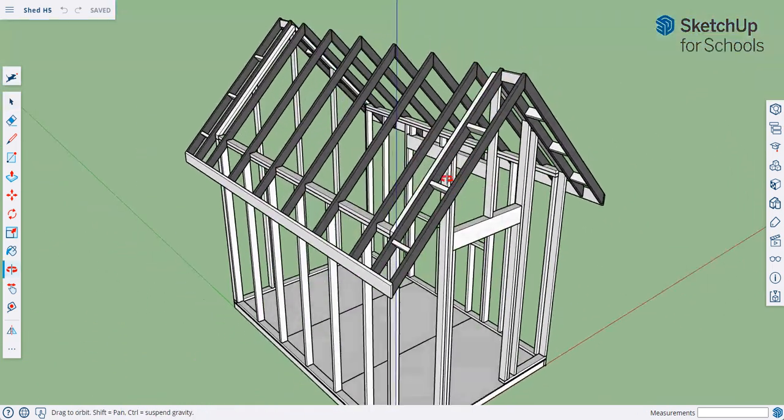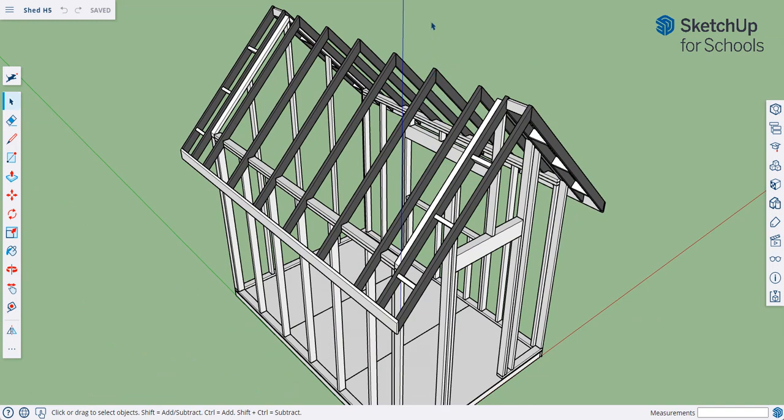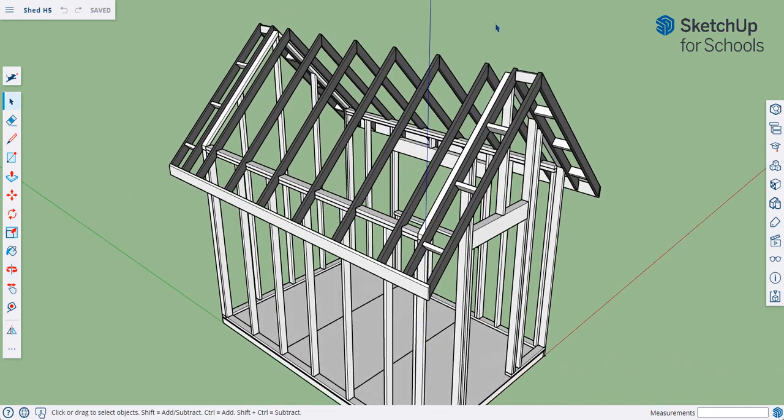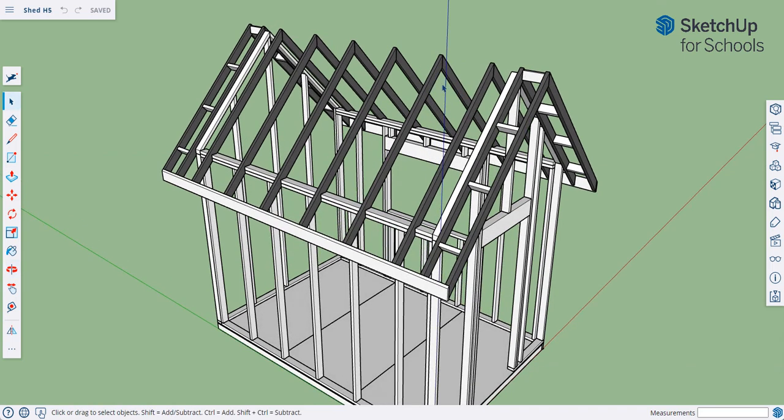So going back to the roof, in order for this roof not to fail, as I showed you in a video on a roof failure, if you don't put what we call collar ties that connect the roof, eventually this roof will fail due to weight. So what we can do is put a horizontal tie, and the engineer will tell you how low that horizontal tie is. So we're just going to do the horizontal tie.